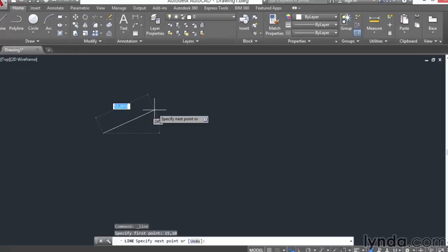Normally we don't do that. We don't care where a line starts from. But I'm just highlighting this to show you that you can actually input absolute coordinates here. Cartesian coordinates aren't so useful when you're drawing lines, but they're more useful when you draw rectangles, and we'll do that shortly.